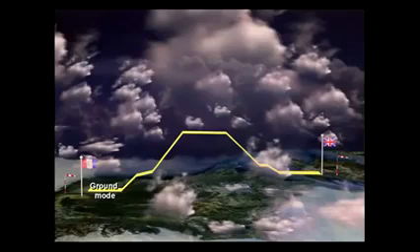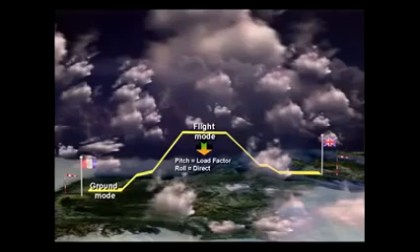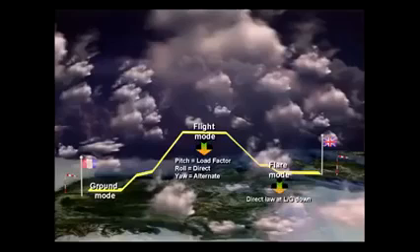Assuming the failure occurs while in flight, pitch control retains load factor demand the same as in normal law. Roll control reverts to direct. Surface deflection is now proportional to side stick deflection. Roll is more sensitive and aircraft reaction is proportional to airspeed. Yaw control: turn coordination is lost and only limited yaw damping is available. Landing mode: aircraft reverts to direct law in all axes if the autopilot is off when the gear is extended.